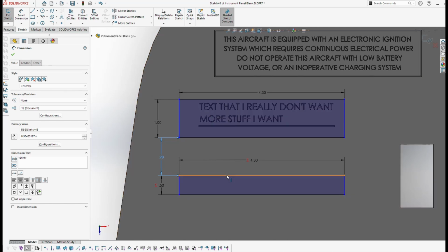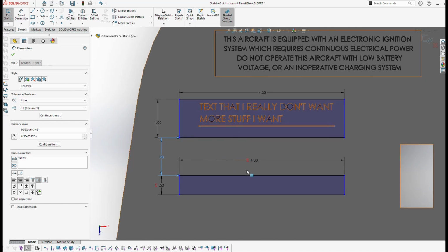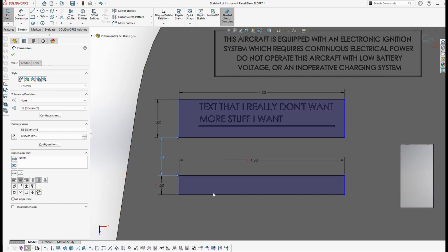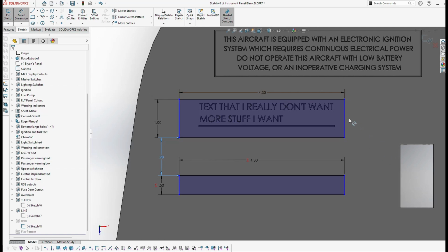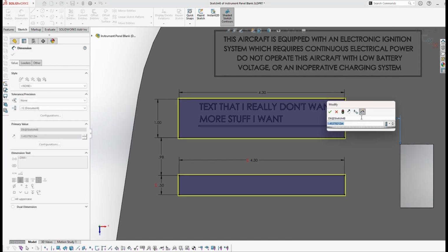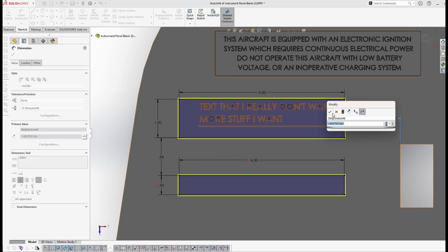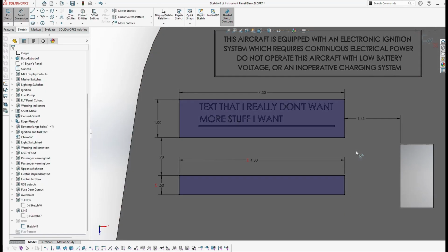Continuing on, so this one is fixed because that one and this one are connected by a dimension, and so is this one, the 1/2 inch, so they're black. I can also dimension this end to a known feature. As soon as I click on that, a bunch of stuff's going to turn black because it's all controlled. If I change this number, of course, everything's going to move.